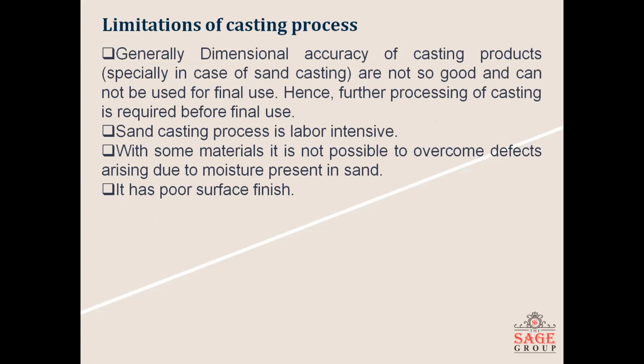Now, what are the limitations? As you can see, there are a number of limitations. The first one is that dimensional accuracy generally cannot be achieved. The casting process is also labor intensive. We require skilled labor for sand casting, because we work with sand that is used for casting.